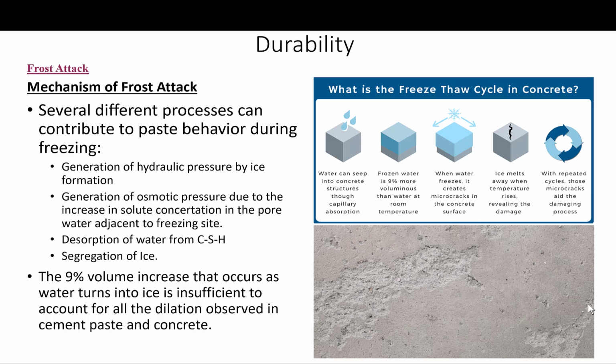As the temperature is progressively lowered, more capillary water is involved in freezing, increasing the hydraulic pressure, and thereby increasing microcracking and dilation. After that, it was actually demonstrated that hydraulic pressure could not really be the major source of damage. It was observed that when, listen to this, partially dry, non-air-entrained paste is frozen, it first shrinks and then expands, even if initially dry enough to provide an empty pore volume great enough to accept that 9% increase in volume. The expansion continues indefinitely, even if the temperature is held constant, while under the same conditions air-entrained cement paste shrinks indefinitely.